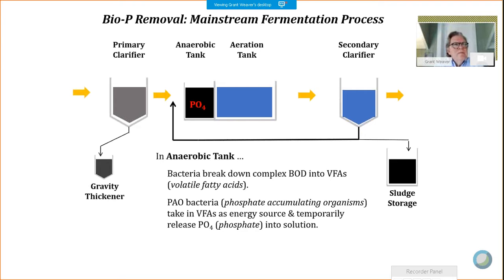So no, I know of a few facilities that monitor VFAs, but most don't. Most instead monitor the production, the activity, the performance of this anaerobic fermented tank by how much phosphorus goes in the solution. And we're going to want about 3 times as much as what comes in. Nice thing is, if you have a spectrophotometer, it's a simple, quick test. Soluble phosphorus test takes maybe 10 minutes. So you can monitor what goes in, monitor what goes out.